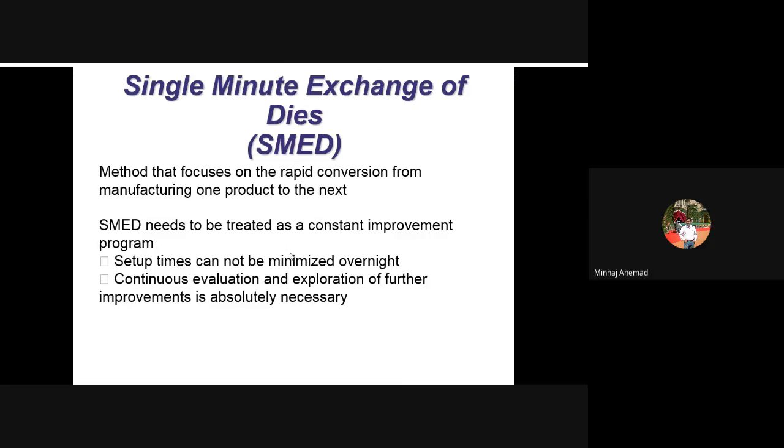There is another concept, single minute exchange of dies, known as SMED. This method focuses on rapid conversion from manufacturing one product to the next. SMED needs to be treated as a constant improvement program. Here the focus is on reduction of setup times. If you want to change from one product type to another, we need so much setup to change the tools, the jigs and fixtures and so on. This SMED method focuses on eliminating that excess time and minimizing it